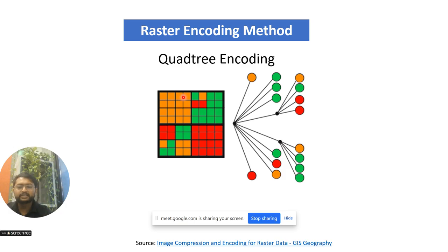After that, I will try to see that the points are distributed across my entire image, and then I will select the function through which I want to do georeferencing. That function is what kind of polynomial function you want to use. And then you have to apply the resampling method, which might be bilinear, quadratic or cubic interpolation. Using that you do the resampling and your image will be converted from one coordinate system to another, or you can say from an image to a real Earth image. Okay, so that is the process of georeferencing.